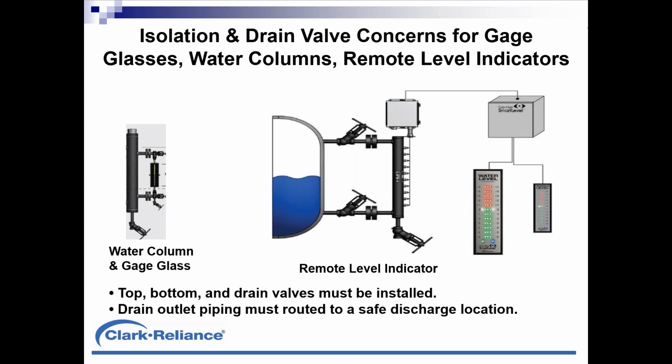However, drain piping going out of those drain valves should be routed to a safe location. A safe location is not a pipe stub aimed right at the operator's feet while they're standing there manipulating the valve. The other problem with short pipe stubs coming off those drains is that as that cloud is forming, even if an operator is wearing a glove, reaching your hand back into that cloud, finding the handle of that valve is not a pleasant thing to do.